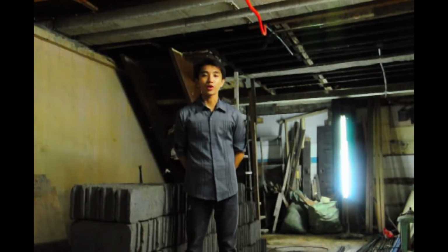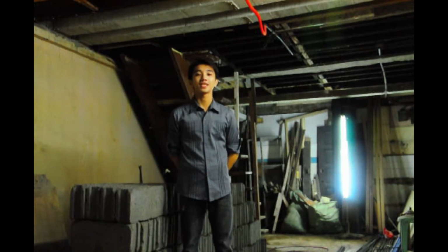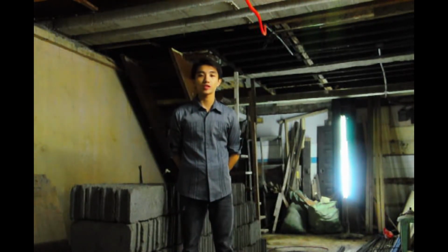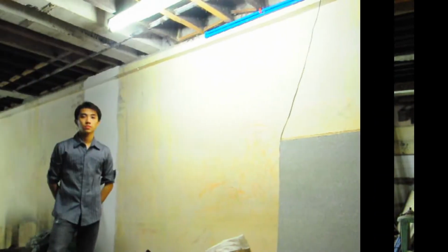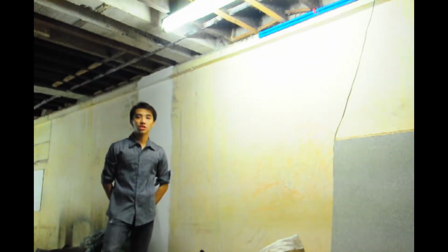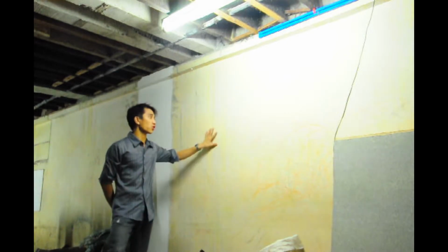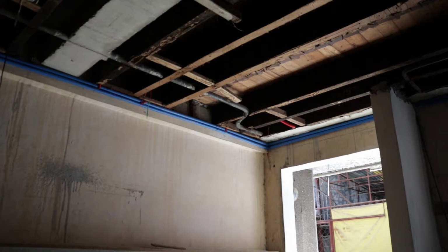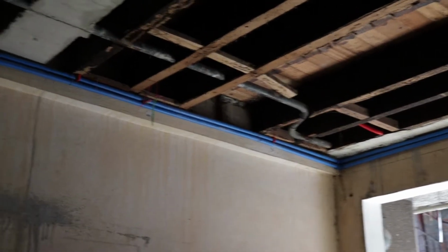According to the owner, this apartment was built in the late 1980s, where timbers are still used in building some parts of the main structure. In here, we can see that the walls were built from reinforced concrete, as well as its girders. The girders are casted along the apartment, which acts as the carrier of the wooden joists, as well as the reinforced concrete walls of the second floor.